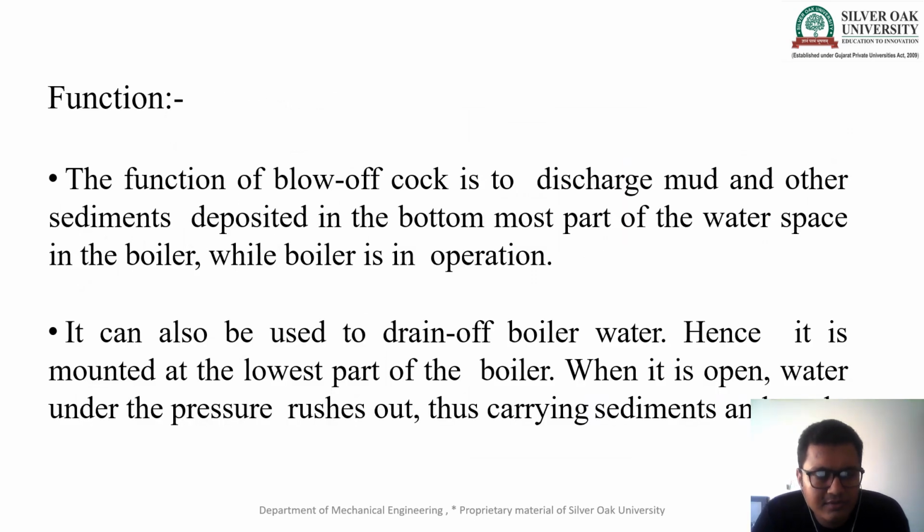Now what is the function of the blow off cock? The function of the blow off cock is to discharge the mud and other sediments deposited in the bottommost part of the water space inside the boiler while the boiler is in operation. Second, it is also used to drain the boiler water. Hence it is mounted at the lowest part of the boiler. We already discussed: when it is open, water under pressure rushes out, carrying the sediments and impurities outside the boiler.